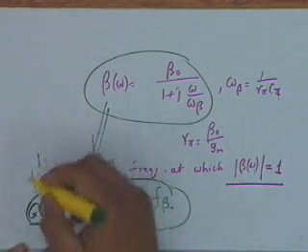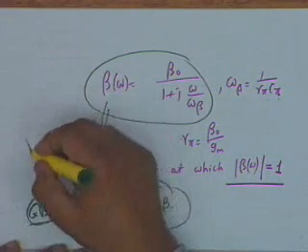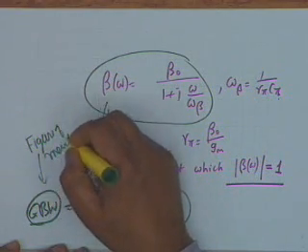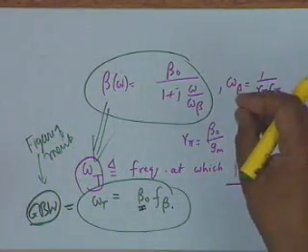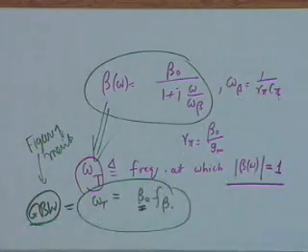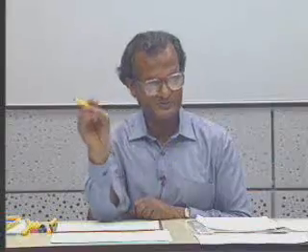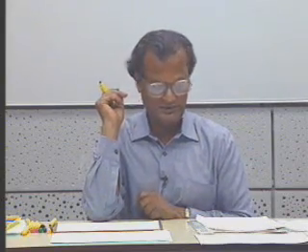The Americans are very fond of many terms for the same quantity. They also call it the figure of merit of a transistor. That can be understood. If you have two transistors in which Ft is 1 megahertz and 10 megahertz, and you want to make a system at 5 megahertz, naturally you will choose the 10 megahertz one. That transistor is more meritorious than the 1 megahertz one. All right, with this we conclude today.